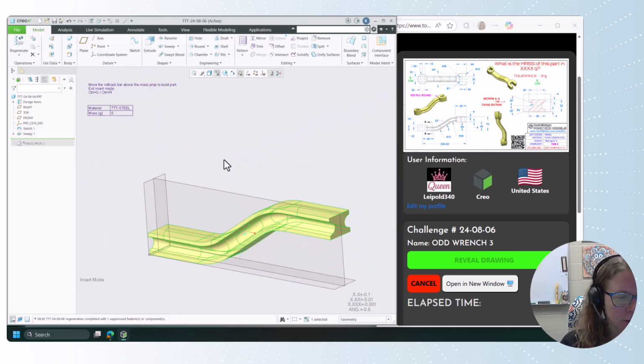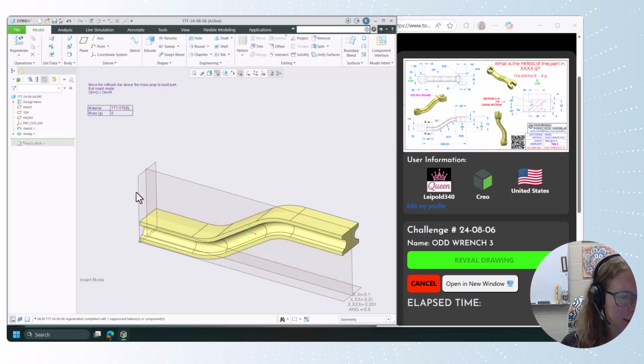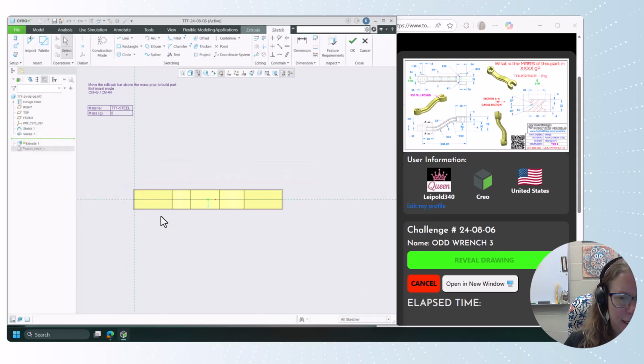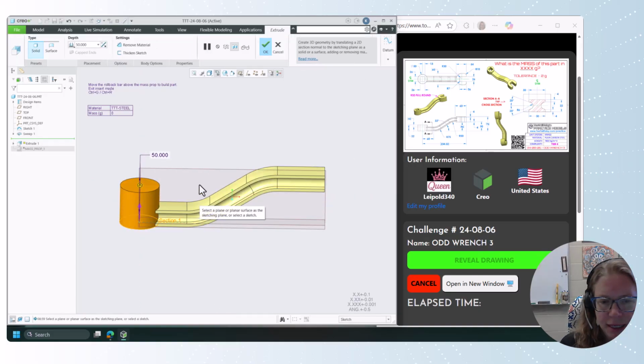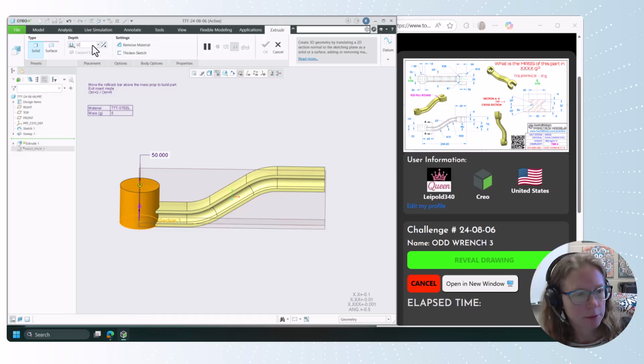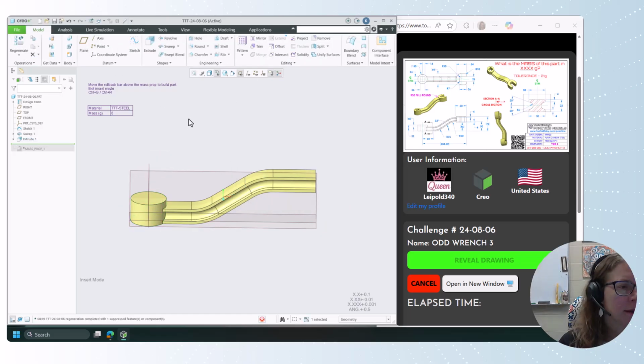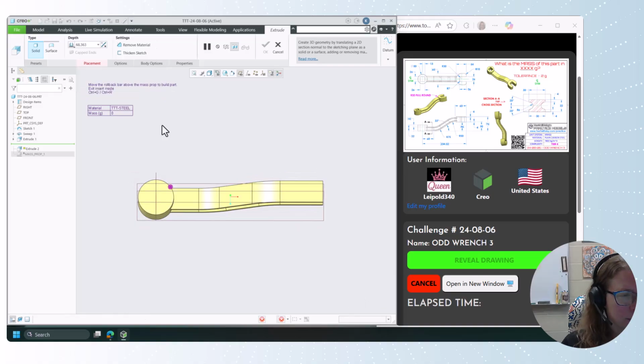All right. So to finish this up, on the left-hand side, we're going to extrude a circle. And that circle on the left-hand side has a diameter of 50. And I'm not going to make the square because I can't add material and remove it at the same time. So we're going to make that come up for a height of 32. And then I can extrude the square.